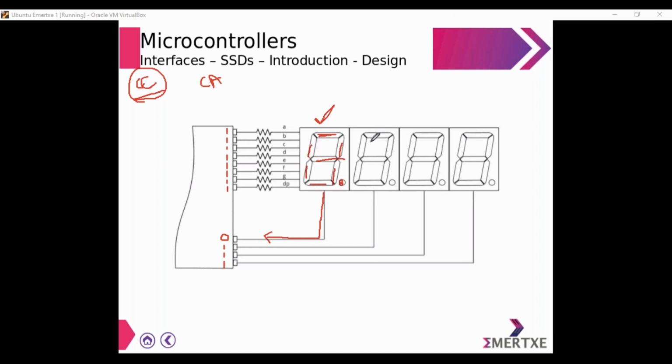Now what happens in this scenario if the current of 8 LEDs is cumulatively moved into a particular pin of the microcontroller? It is going to damage that particular pin of the microcontroller, isn't it? So what is the solution to this? I have to be providing the ground differently.